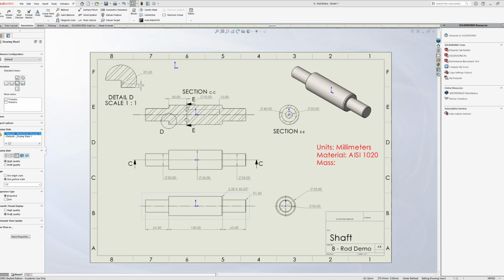So if anybody is still having issues saving assemblies or doing the pack and go, it might be worthwhile to try to do a repair. That shouldn't mean that you need to reinstall. You would just need to go to the installation SolidWorks wizard, and it should have a repair option in there. That's assuming you even want to do it.